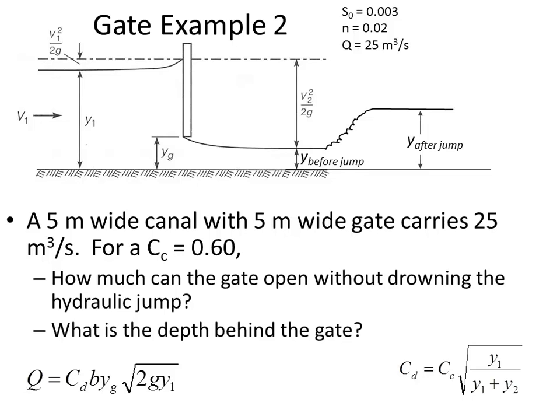Okay. We're headed in the right direction. In this case, it was subcritical. What if it had been really steep, and what if, when we did our calculations, we found that the critical depth is up here, and the normal depth was down here. So here is our gate. What would happen if you've got a steep slope and the conditions downstream are supercritical?